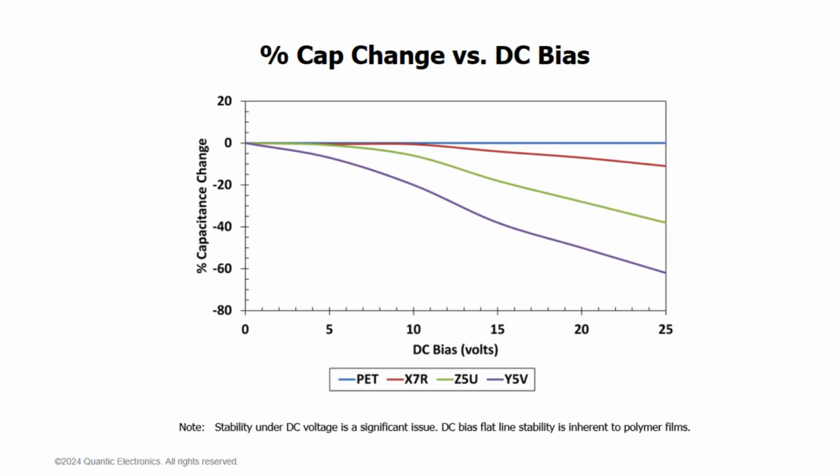And an increasingly significant consideration as we go up in voltage is the DC bias effect. Now, with some types of X7Rs, there can be a decrease as much as 80% of your effective capacitance in the circuit at 400 volts, 40% at 100 volts. This, again, is loosely related to the high dielectric constant of the material, and the dielectric thickness of the material also plays a factor.